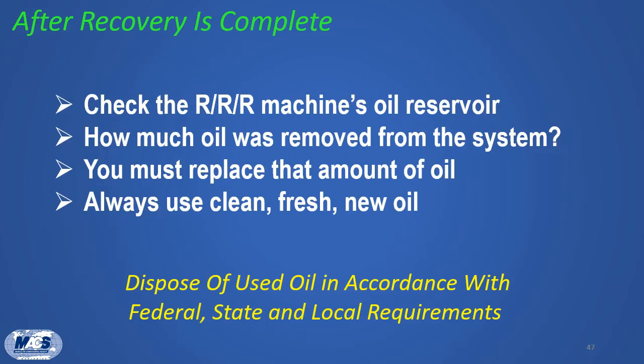After recovery is complete, you'll want to make sure you check the RRR machine's oil reservoir. That's how you can tell how much oil was removed from the system, because whatever amount was removed, you have to replace that same amount of oil with clean, fresh, new oil. And make sure that you dispose of the used oil in accordance with any federal, state, and local requirements.